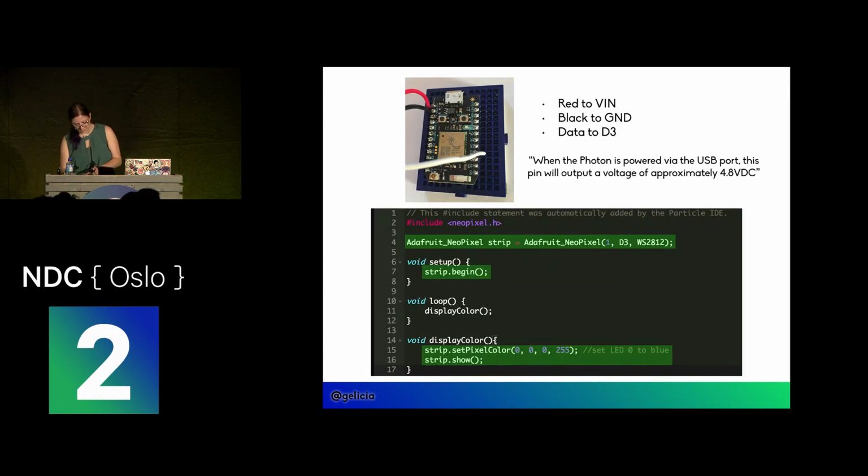So with those 3 wires and that LED, you take the photon, which I put somewhere right here. And there's different pins on this. There's D pins and there's A pins, which is digital or analog. Now, most of the time you're using digital pins, just because for these things, they use a library to transmit what you want it to do, and it goes through the library and then transmits the ones and zeros to communicate with everything for you. So you mostly just use the digital pins.